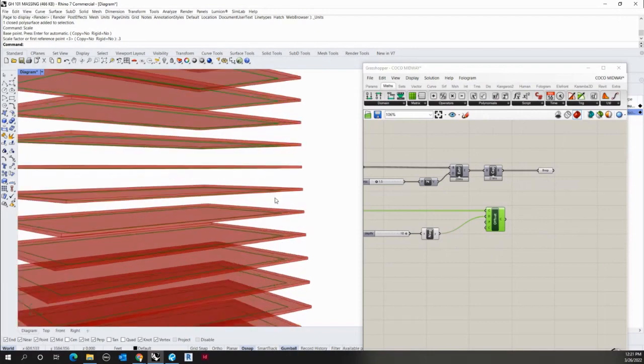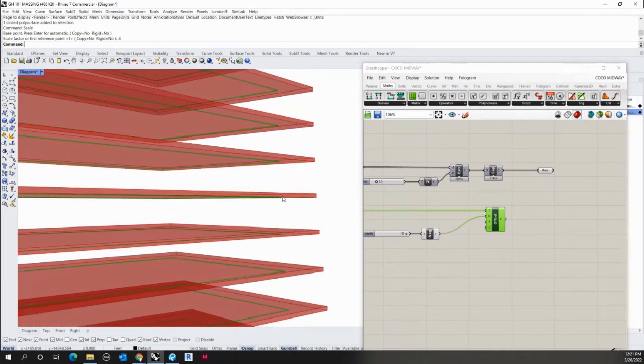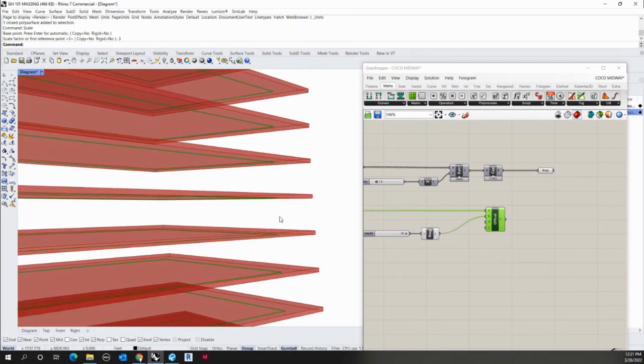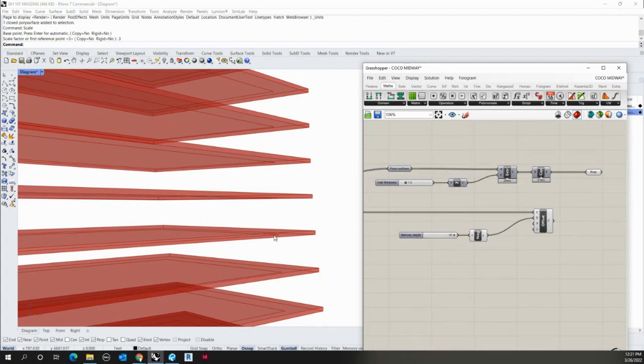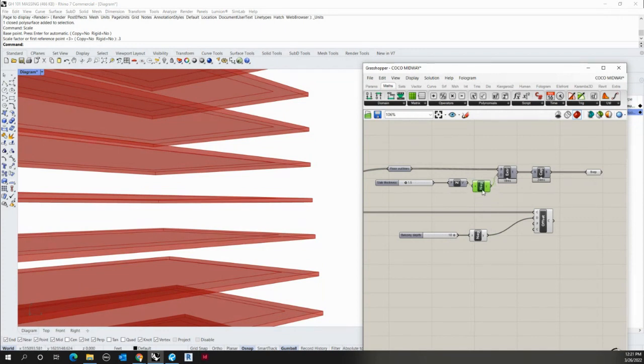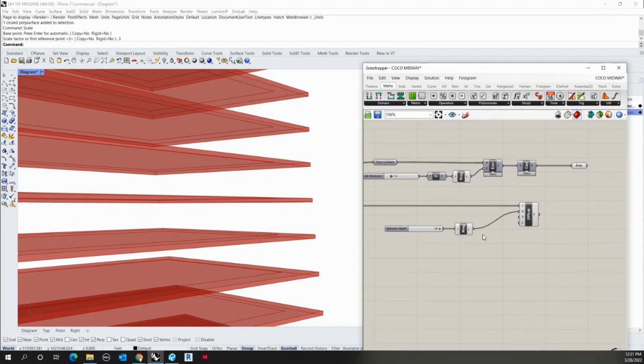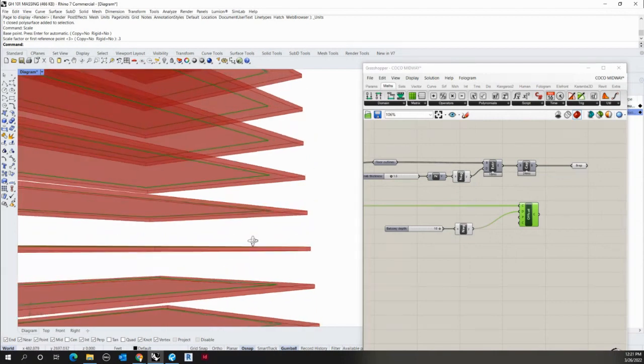And you can see they are at the top because we extruded our slabs up. So we could do something similar here where we want to extrude our slabs down, because typically you define the kind of finished floor height. So I'll use this negative component here, copy it and use it there. So now I'm extruding down. So I go in the negative Z direction. And now our curves are on top of the slab.